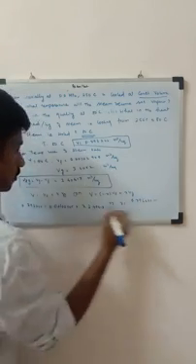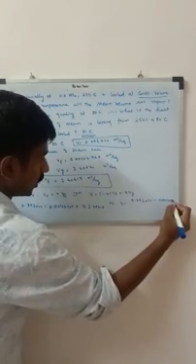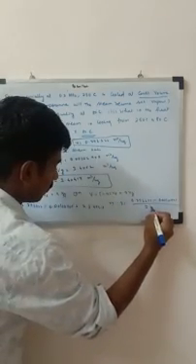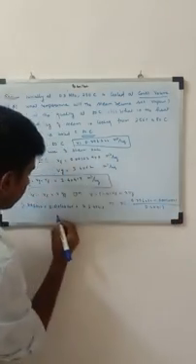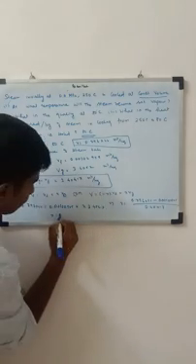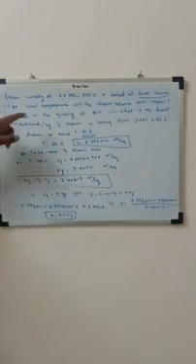I'm going to bring it to this side, so x is equal to 0.796244 minus this value 0.0010295, divided by this value 3.40417. So therefore, I get my x value as 0.232. So this is the quality of steam at 80 degrees.